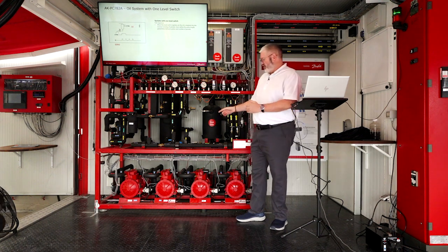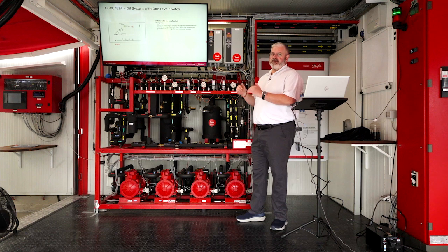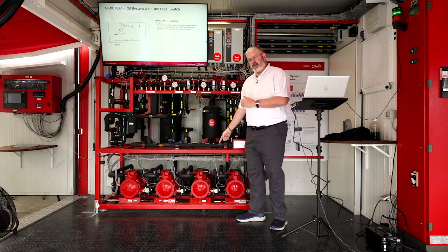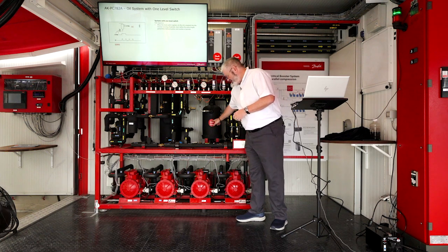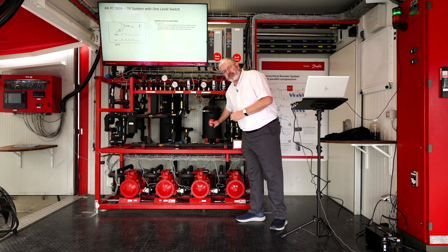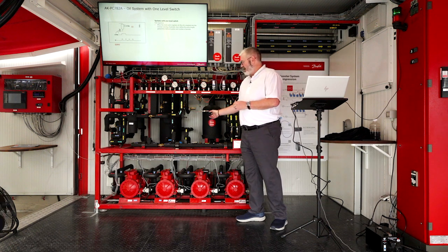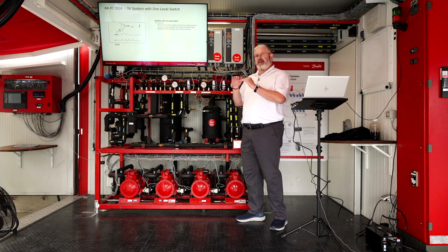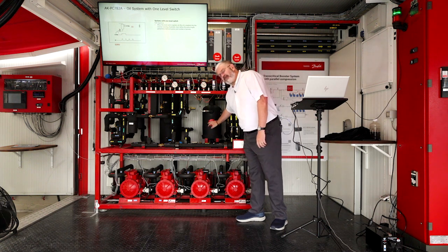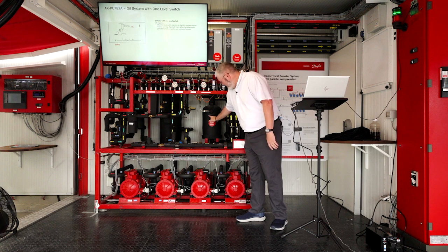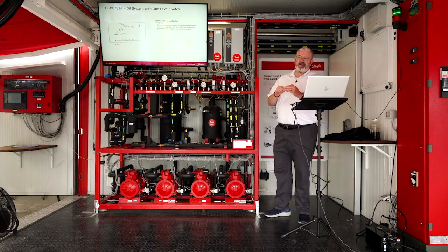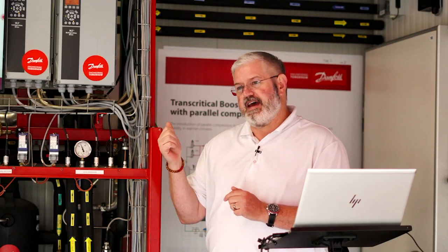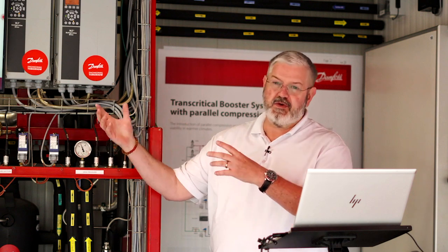One thing to note on the reservoir, you don't want to have 1,300 pounds in the oil separator being what feeds the compressors, 900 pounds pressure drop across your oil solenoids. So this oil reservoir is actually vented at flash tank pressure. It's got a line that goes to the flash tank to stay at the same pressure. So in our example, this is at 520 pounds pressure at all times because there's a line going over to the flash tank. If you think about that venting over there, there's actually a little bit of load from that dumps into that medium temp suction that we don't show, but there is a little bit going over there as well.